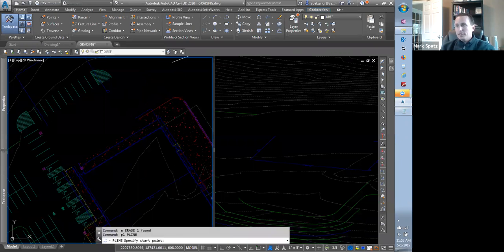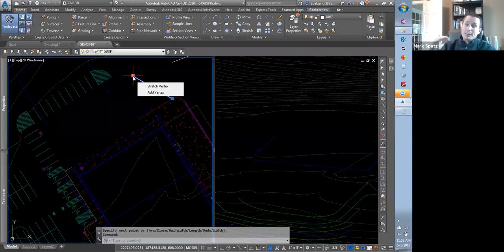I'm going to draw a polyline, my OSNAP Z, my elevation, my planar elevation that I'm telling things to draw is at 608. I turn my OSNAP Z back on, and I'm going to do a polyline again and snap to the end of this curve radius, pick over here. Now if I pick on that, even though I snap to an object that's at elevation 0, because my OSNAP Z is now turned on, it's actually going to draw everything at 608.